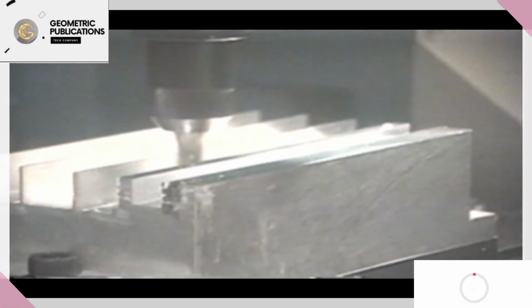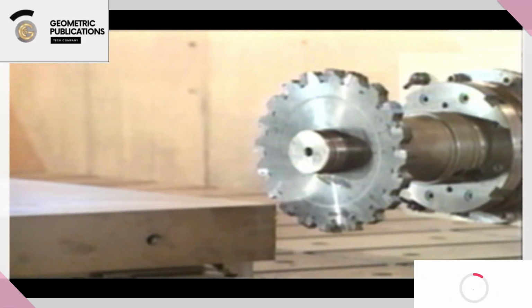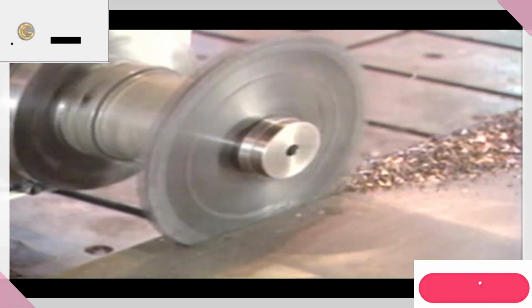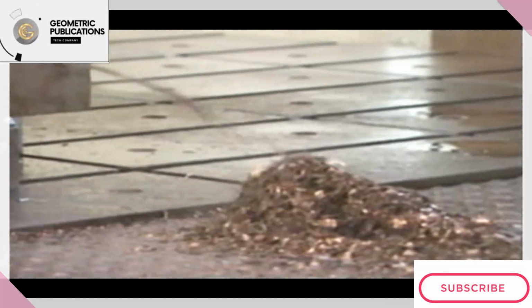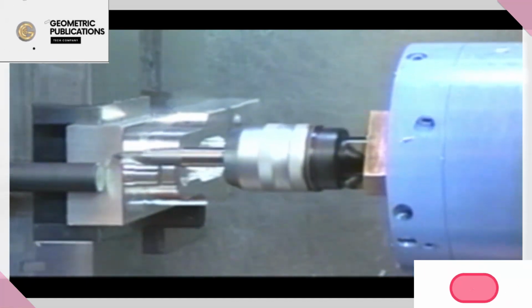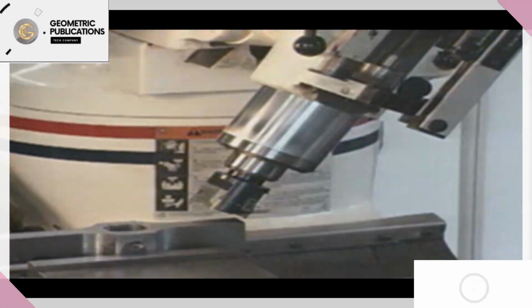Deep, narrow slots may be milled with an end mill, a thin slitting cutter, or a grooving cutter. Grooving or slotting cutters are generally more efficient than end mills in cutting long and deep slots because of their larger diameter and greater number of teeth. Chamfers may be produced with the chamfering end mill, which breaks the sharp edges of the workpiece with a 45-degree angle cut. Chamfers can also be generated using end mills, form peripheral milling cutters, long edge cutters, or face mills angled 45 degrees to the work surface.